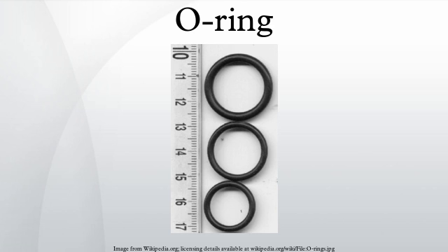NBR is generally not resistant to aromatic and chlorinated hydrocarbons, fuels with a high aromatic content, polar solvents, glycol-based brake fluids and non-flammable hydraulic fluids. NBR also has low resistance to ozone, weathering and aging. HNBR has considerable improvement of the resistance to heat, ozone and aging, and gives it good mechanical properties.